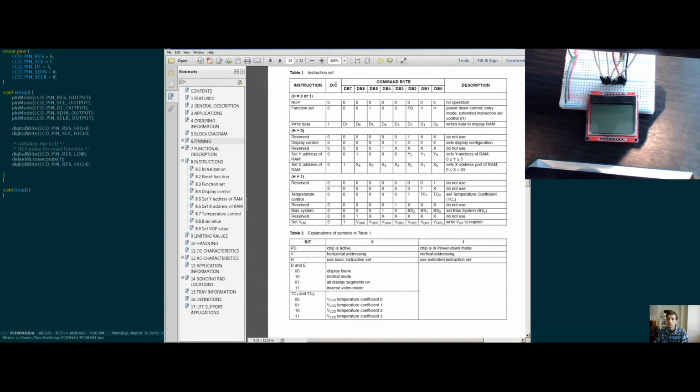So we can see if this PD bit is set to 1, then the chip is in power down mode. But we of course want it in active mode so that the LCD can actually show pixels. We will want to set that to 0. For the addressing, I guess we can look at that now.